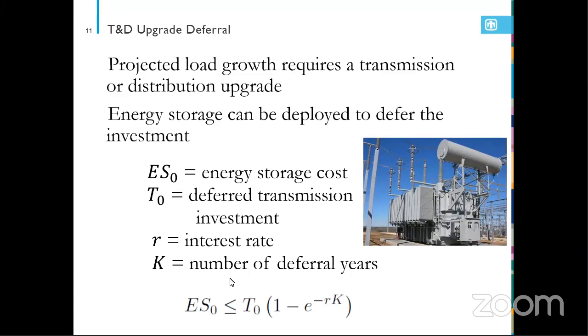So that was one of the reasons people started looking at value stacking. I've got assets sitting there and I'm only using it a couple hours a year. What else can I do with it? That can be good, to use the storage for other applications, but you also have to keep in mind that oftentimes those other applications might not provide as much value. And if you degrade the battery system and reduce the lifetime, it actually might not make sense to use it for other applications when all factors are considered.